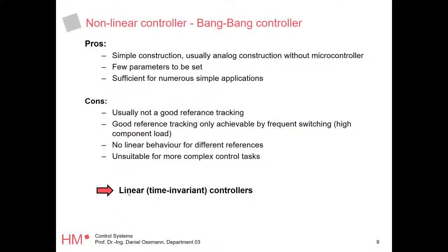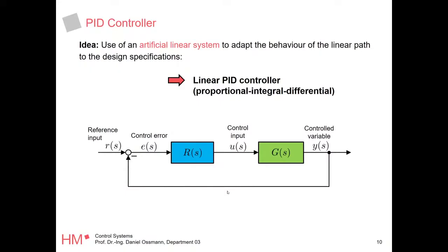So we said next stop, so to say, linear time invariant controllers. Because we are now back in linear system theory, we are basically allowed to write here G of S and R of S. This is a small but important detail. If your system is non-linear, there's actually no Laplace domain. You are not allowed to write a transfer function as soon as you have a non-linear system.